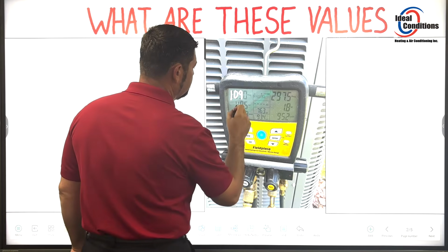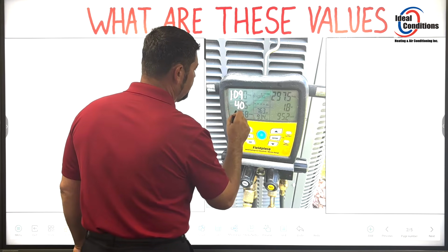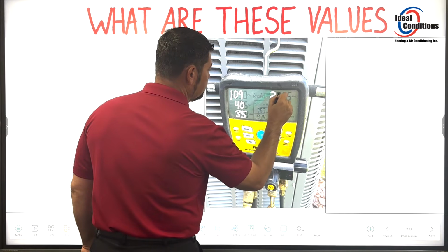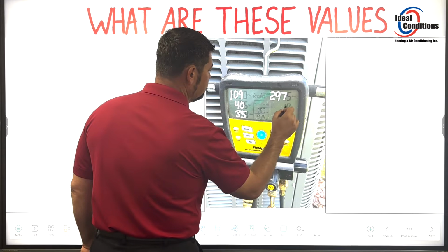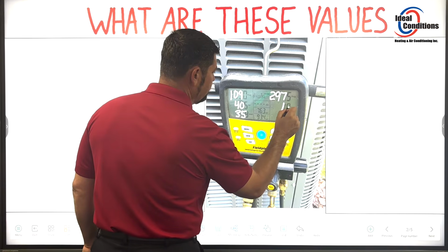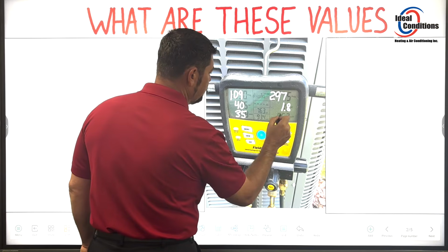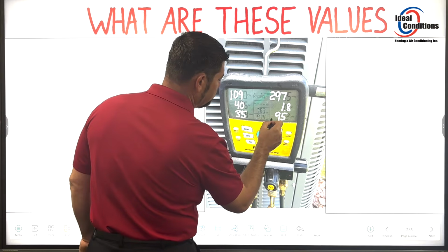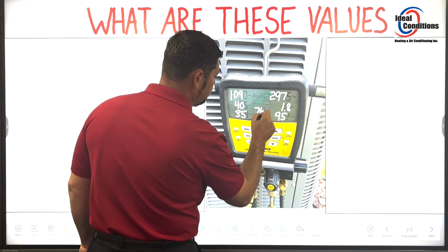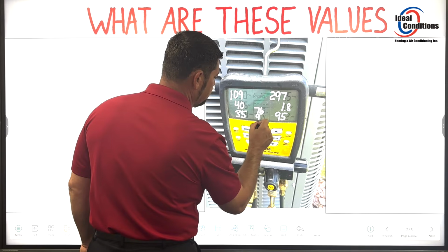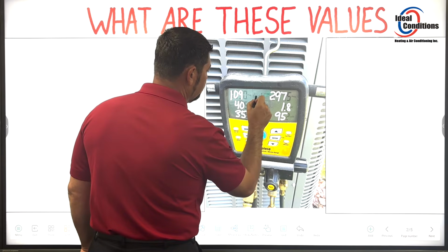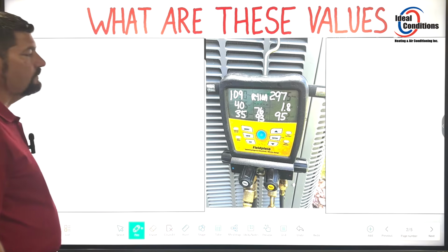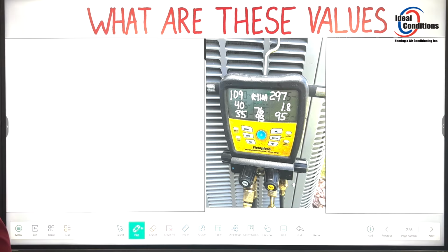I have 109, I have 40, I have 35, I have 297, I have 1.2, and I have 95. Suction line temperature is 76. Liquid line temperature is 93. And this is R410A. And hopefully that shows up very good for you.